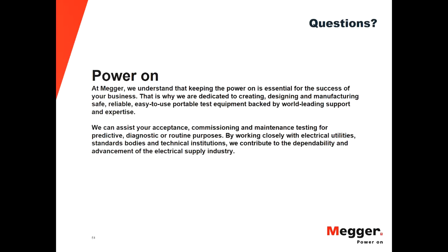You're not just running the test to measure the capacity, and that's why I was also mentioning that there's a lot of information in the test that you can use to analyze your results further, beyond the capacity result. Another thing to consider is that the float voltage is really a test on the charger. You are verifying that your charger is properly set.